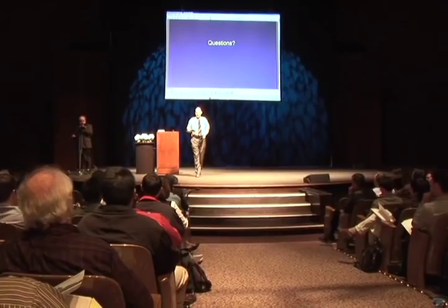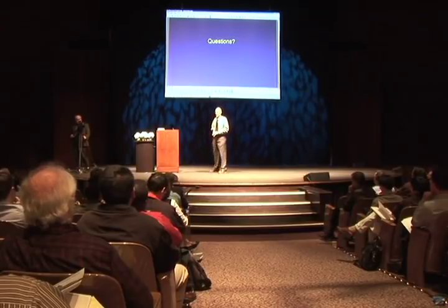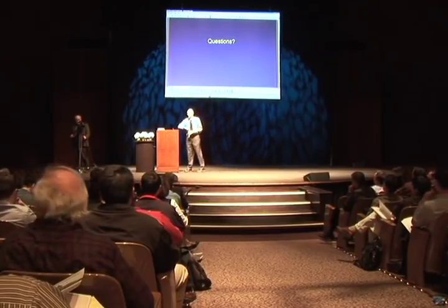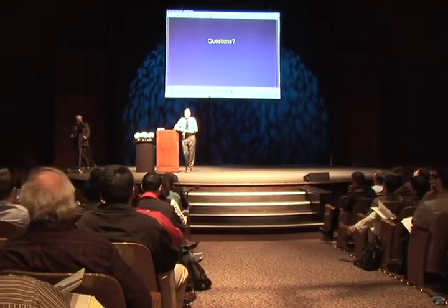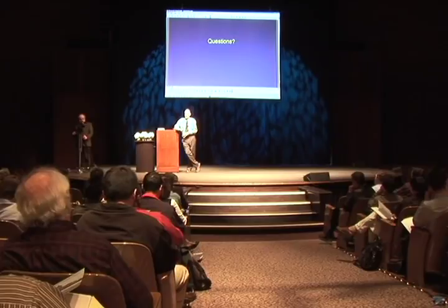Oh, anywhere. You can go online and get them. Choosing the records is a bit of a black art. This is a matter of debate. If you have these 7 records, there are certain rules that ASCE 41 and other documents establish that you should follow. But it is admittedly possible to kind of cherry pick your earthquakes a little bit. This is a matter of intense debate in the academic community about exactly how you pick the earthquakes, and this is something of an unresolved issue.